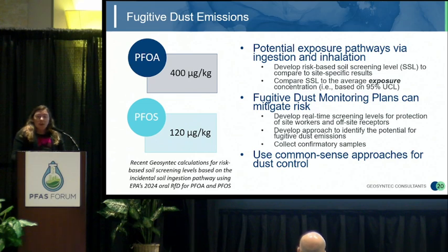And then you would compare your site-specific data to that screening level, and if it exceeds it, then that means that it's likely that there is a potential risk of exposure, and if it's well below that, then it's unlikely that there would be a human health risk if ingested during construction.